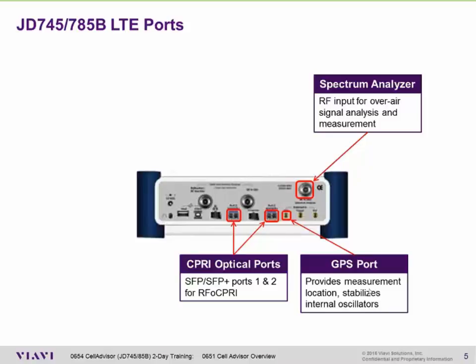The reason for that, please do not underestimate the capability of our GPS chipset that we've integrated into our product. Very often, I will uncoil that GPS cord that's actually a coax, so I take out the inductive properties and keep the floor away from other sources of electronics, meaning laptops, power supplies, projectors, even our test equipment. I have been amazed how many times I've otherwise gotten GPS reception in rooms with no windows. So please take advantage of that.